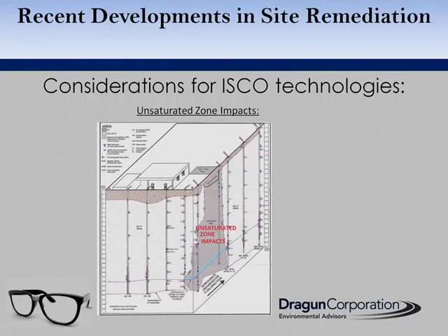The minimal acceptable radius of influence is usually between 3 and 4 meters for an efficient remediation project, just as a rule of thumb. This range of radius of influence is not typically far-fetched when injecting below the water table, because here the majority of the void spaces, soil grains, is saturated with water, and this can help disperse the oxidant. Injecting into the vadose zone or the unsaturated zone is impractical, as these void spaces here are not saturated, and this would reduce the spread of the injected oxidant.